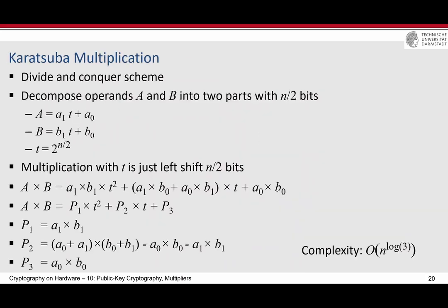Good. Now, one thing which is important to know is that when the operands are super large, for example, in RSA you have 2048 bits as the operand, then the multiplication is not that cheap, either in hardware or software. But there is a scheme which is called Karatsuba multiplication or multiplier, which makes it easier and can also be used in a recursive way.